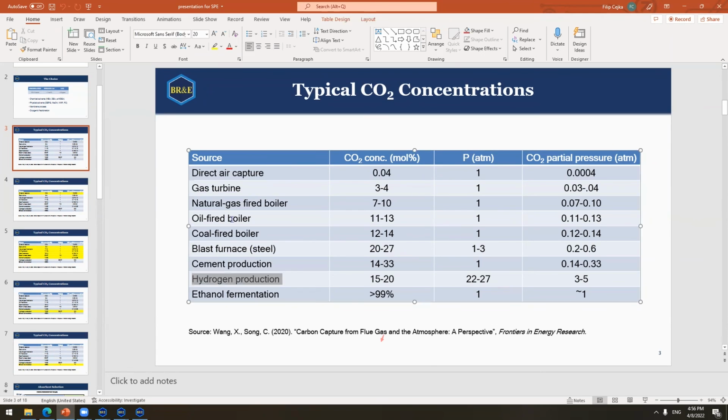For hydrogen production with a gas turbine, if you want to capture the CO2 from the gas turbine, then you will probably need about an 8 meter diameter column, and it's going to be about 20 meters high. And because you're working with a very low pressure here, you can't use just trays because they would have a very high pressure drop. So then you need to think about packing, and that can get really expensive. So that's something that will be very costly.